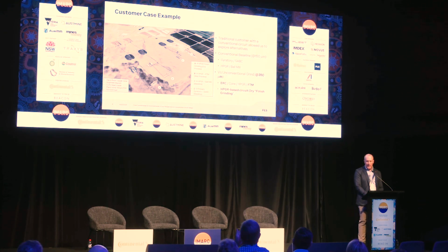So we incorporated two technologies there, or two flow sheets, a wet and a dry circuit, where we took an ERC and we added an FTM, a tower mill, at the end. And then we also looked at an HPGR-based dry finish grinding circuit, where we take the HPGR product to 150 or 350 microns. That study is still in progress, so we're not really going to focus on that, but we'll have a look at what we got with the ERC solution and what we did there.